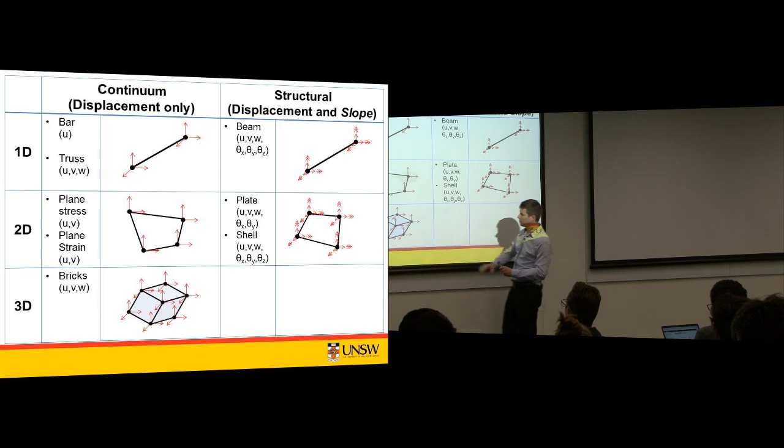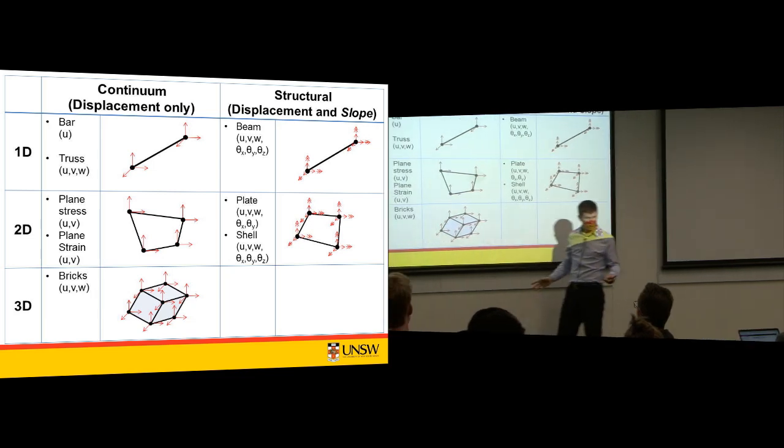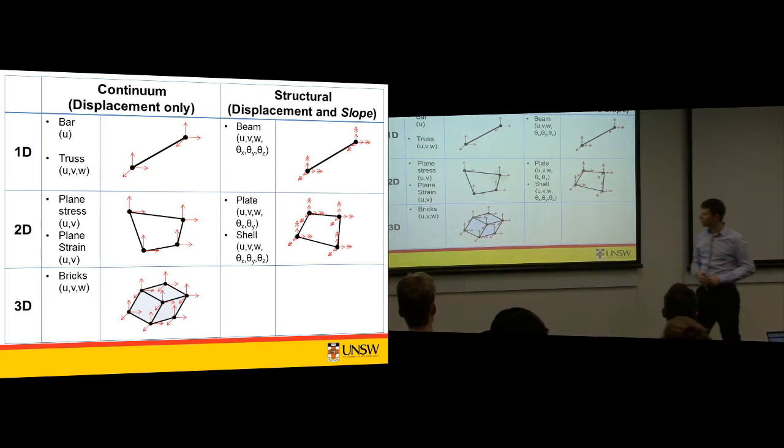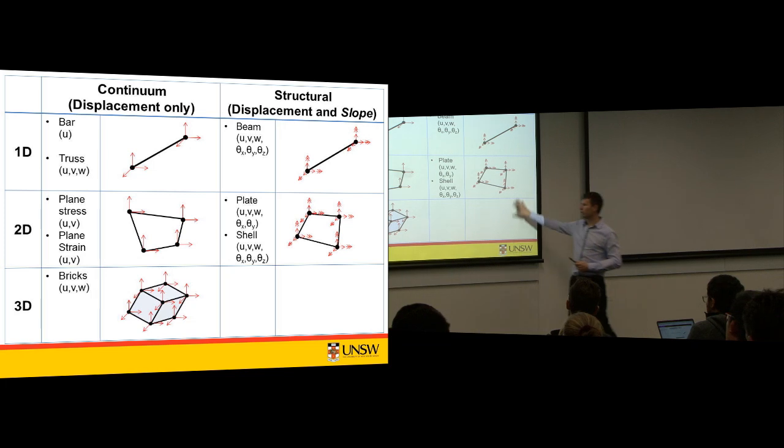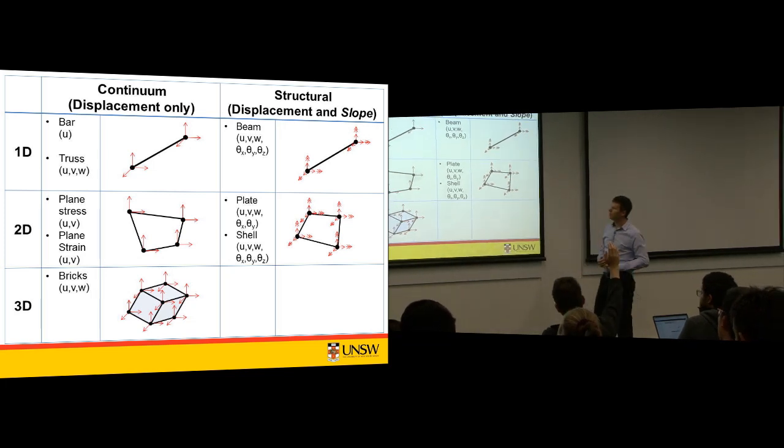Some people say, well, we've just got bricks, so let's use bricks all the time. As we go through, we'll learn that's not wise. A, it's very computationally expensive, and B, the results may not be as accurate as a well-defined shell, for example.